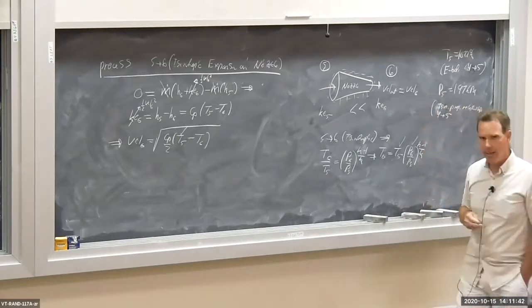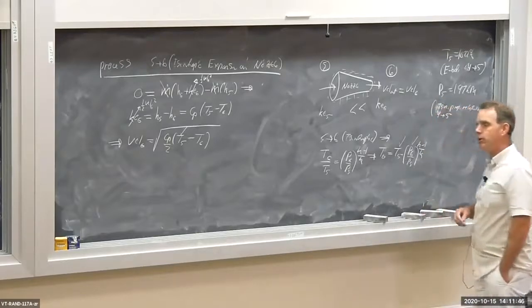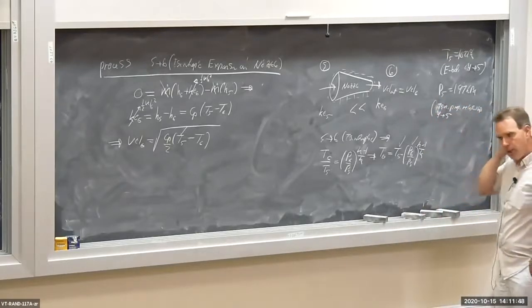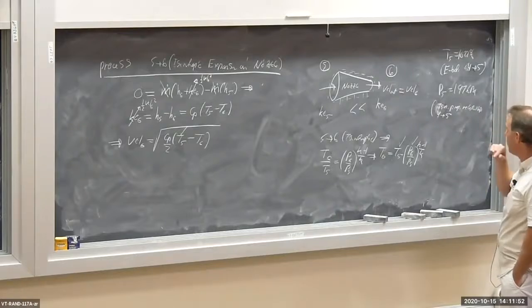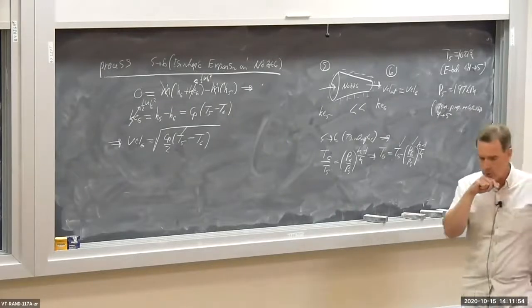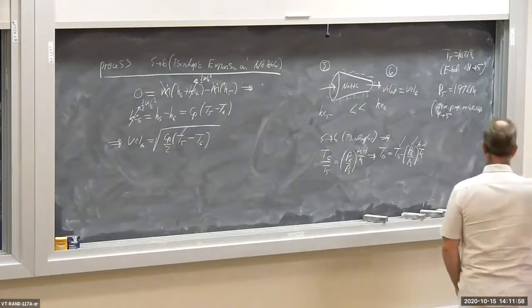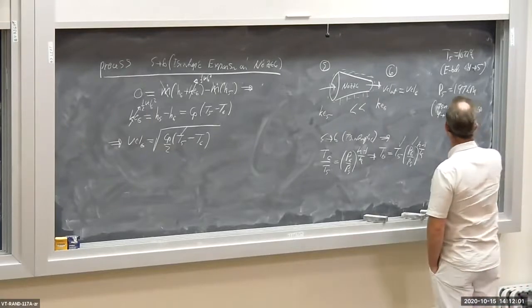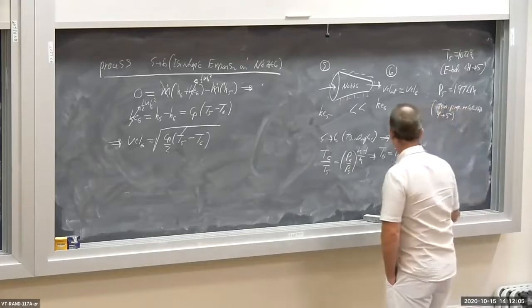That's in the turbine. I know the maximum temperature, the turbine inlet temperature, it's like 1200 degrees. I know the outlet temperature, T5, so I can get the pressure drop across the turbine, and therefore I can get P5. Okay? So I have everything here.